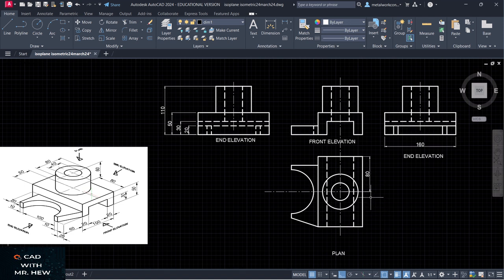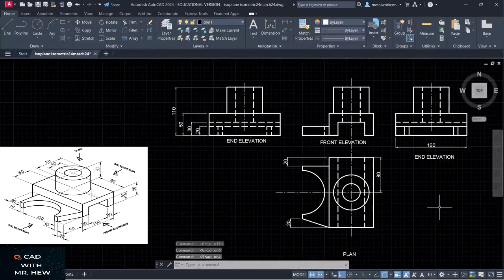Then the next measurement we're going to put on is 20 millimeters. So we press enter because it's a linear measurement, to get the last command. Come, and I'm going to put the 20 right out here. Okay. Then I'm going to measure the other 20 millimeters down here. That's 20. Enter. All right, so I'm going to put the length here on the plan.